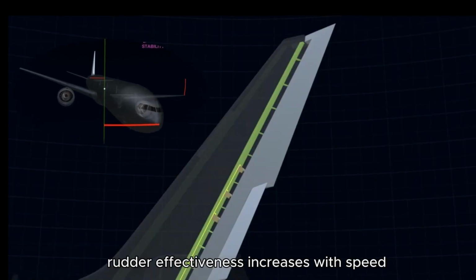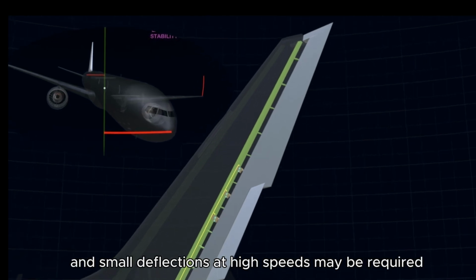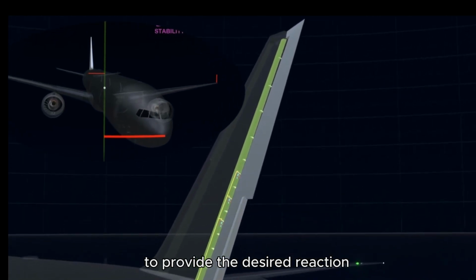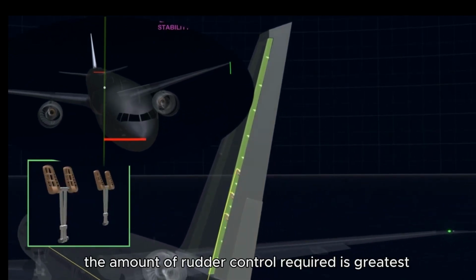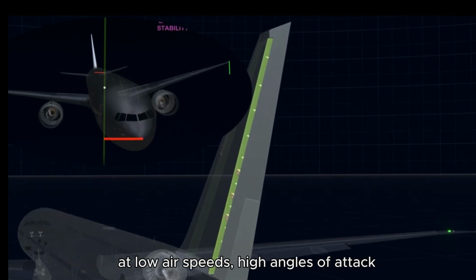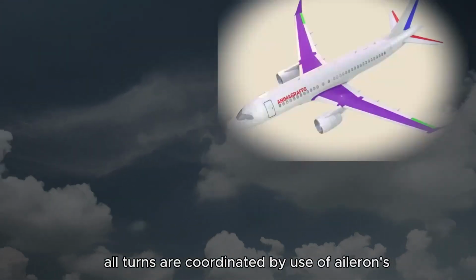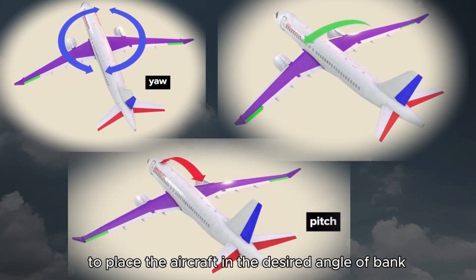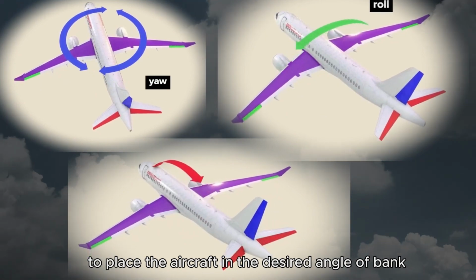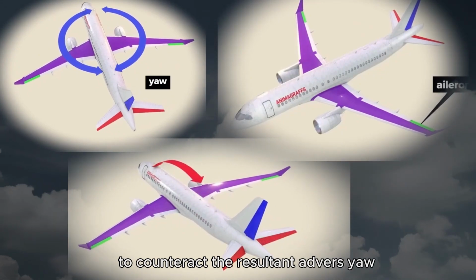Rudder effectiveness increases with speed. Therefore, large deflections at low speeds and small deflections at high speeds may be required to provide the desired reaction. Application of the rudder is used to counteract adverse yaw. The amount of rudder control required is greatest at low airspeeds, high angles of attack, and with large aileron deflections. All turns are coordinated by use of ailerons, rudder, and elevator. Applying aileron pressure is necessary to place the aircraft in the desired angle of bank, while simultaneous application of rudder pressure is necessary to counteract the resultant adverse yaw.